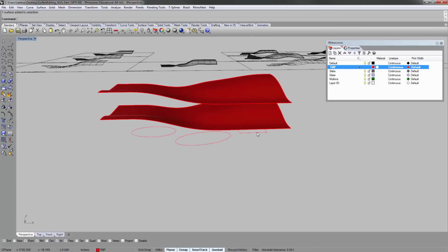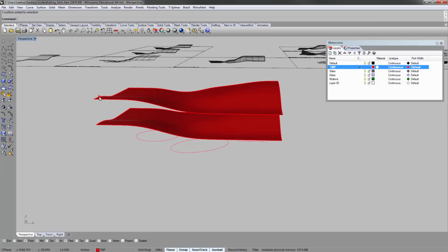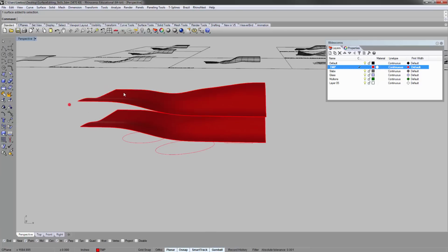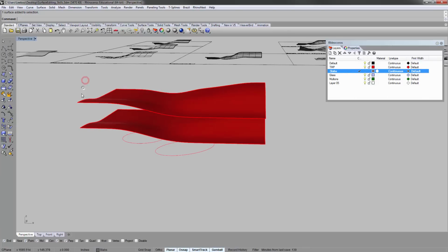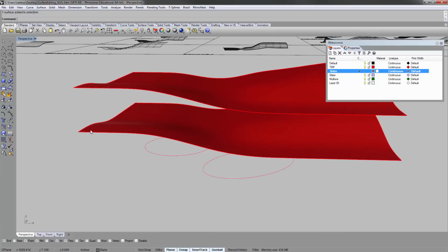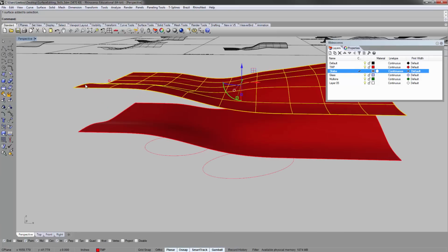So these are actually going to be what I use for the Boolean or cutout operations for the floor slabs. But this is going to be the floor-to-floor height. So let's switch over to the slab layer, and let's take this. Actually, offset surface or extrude surface will both work because these are going vertically.